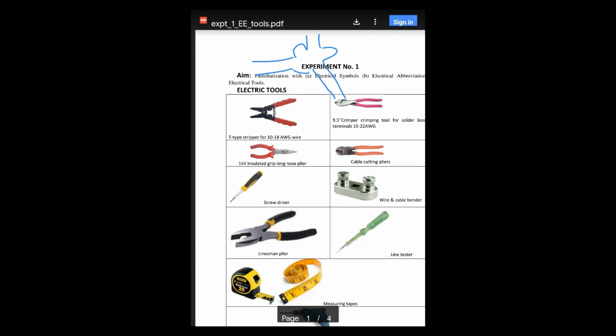Suppose this is our junction box, and wires are here, and wires are going towards the load. You can say, okay, this is going for a fan, and this is going for, say, an LED bulb, and so on. But at the construction stage of any home or flat, we make junctions, and surplus supply wires are left at the junctions for future use.